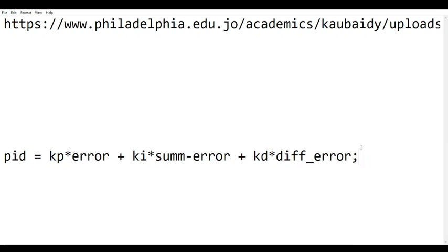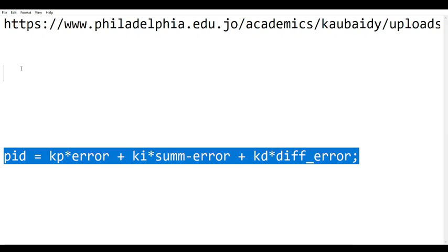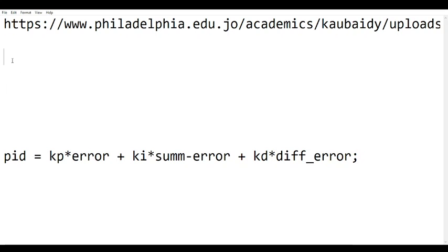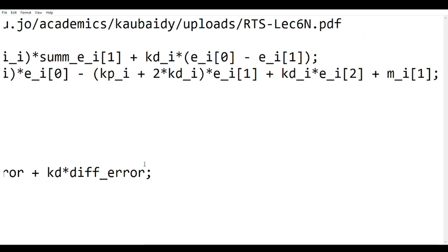For DC motors, I find the position form works just fine, but for DC-DC converters that have much faster control loops, the velocity form is much better to use. So now I'm just going to put back what I removed.